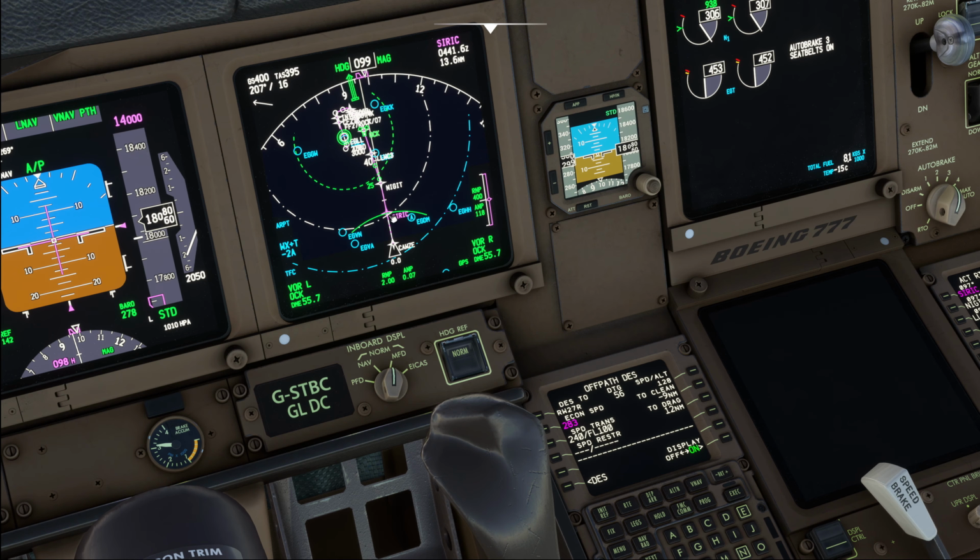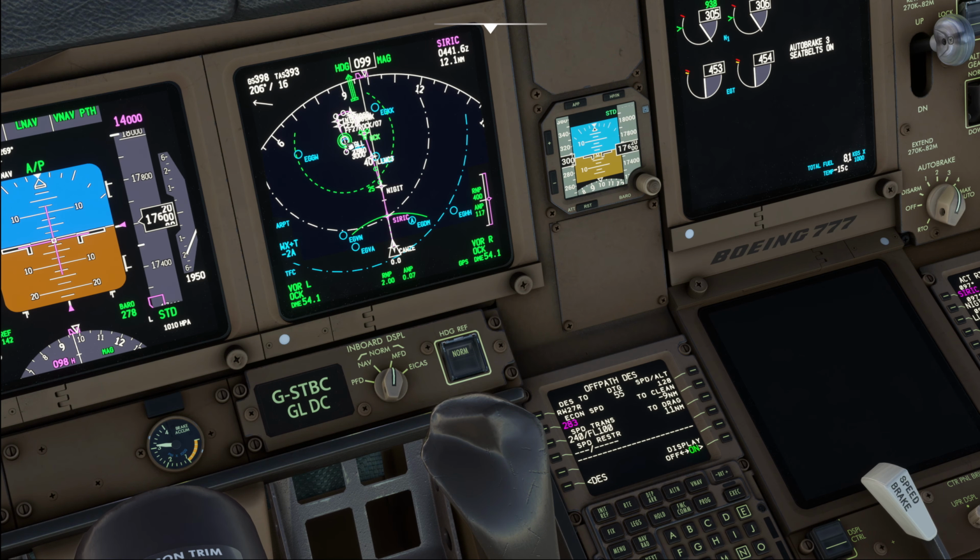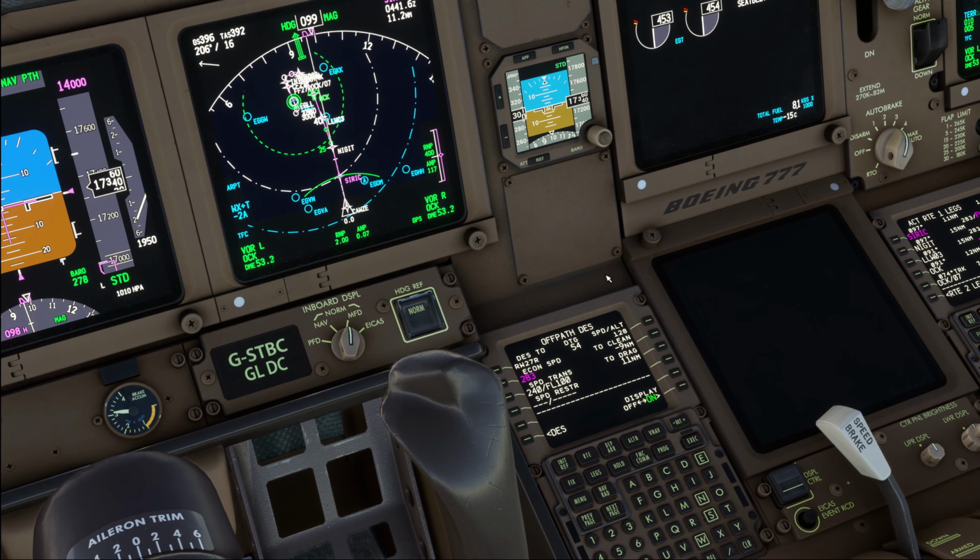However, when using this feature, be aware that the landing runway, or the target waypoint, is always taken as a direct distance. So you can see over here, distance to go 55 miles. That's direct from here to there. It does not take into account that we have to fly around the airport and come back for landing. So just be sure to know how you're using this feature.